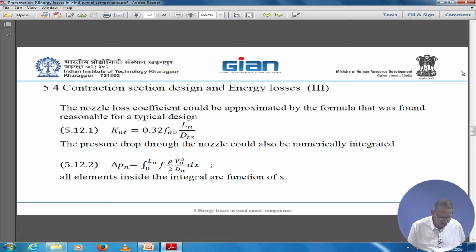So we have a calculation, a formula to calculate the loss in a mesh. It has two factors. One is K mesh, which is taken as 1.3, just like that, and the other, K Rn, is formulated empirically as a factor of Reynolds number for the wires. And you see that for higher Reynolds numbers, this factor is 1 only, and the other one is close to it.